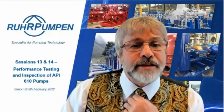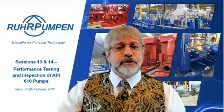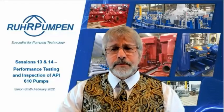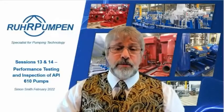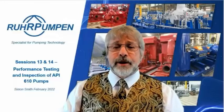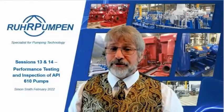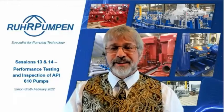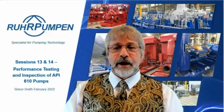Milagros and Antunes do Maiolo, excuse me if I've pronounced that wrong, I know I have. How is the seal flush plan tested? How should it be requested as part of auxiliary tests? If you're using a plan 52 or plan 53, yeah, you need to discuss it with the manufacturer first. He needs to be able to be sure that he can fill it with the correct barrier fluid. It's got to be cleaned out again afterwards. You've got to have the correct pressure of nitrogen. It can be carried out, yeah.